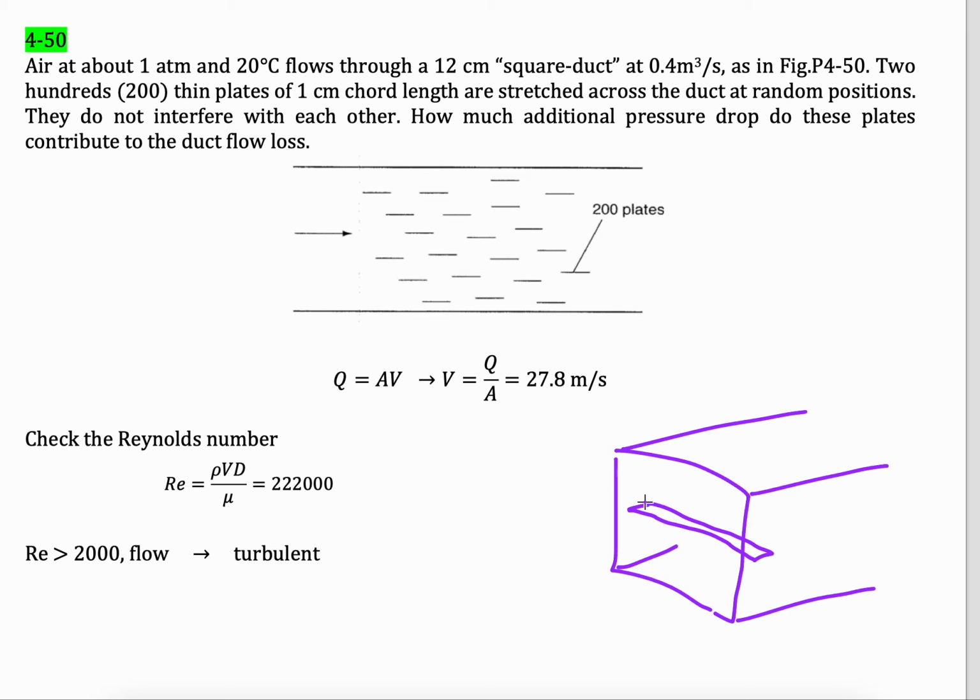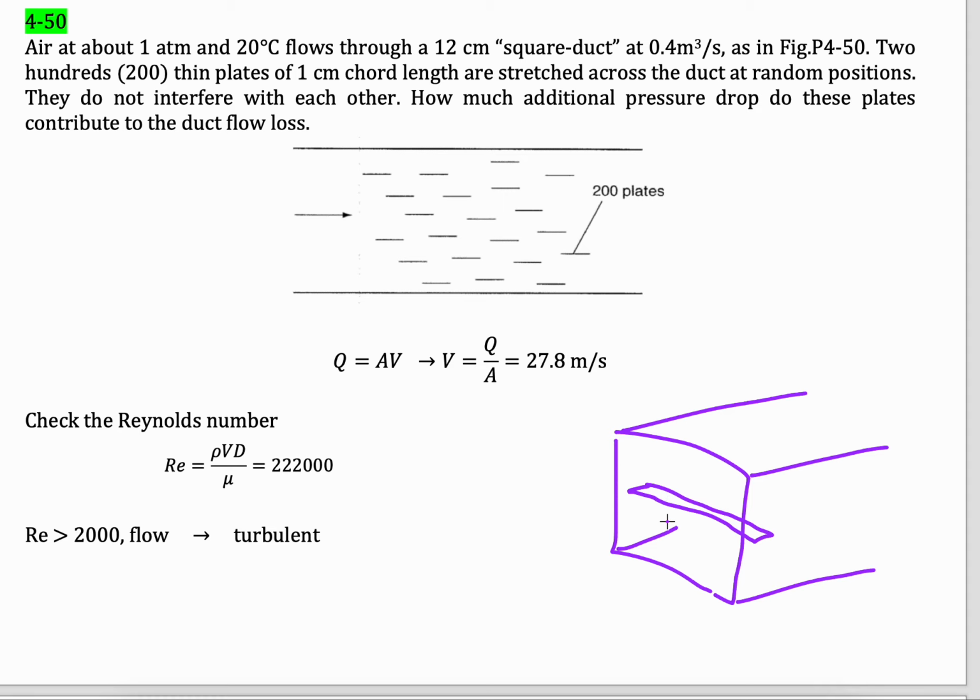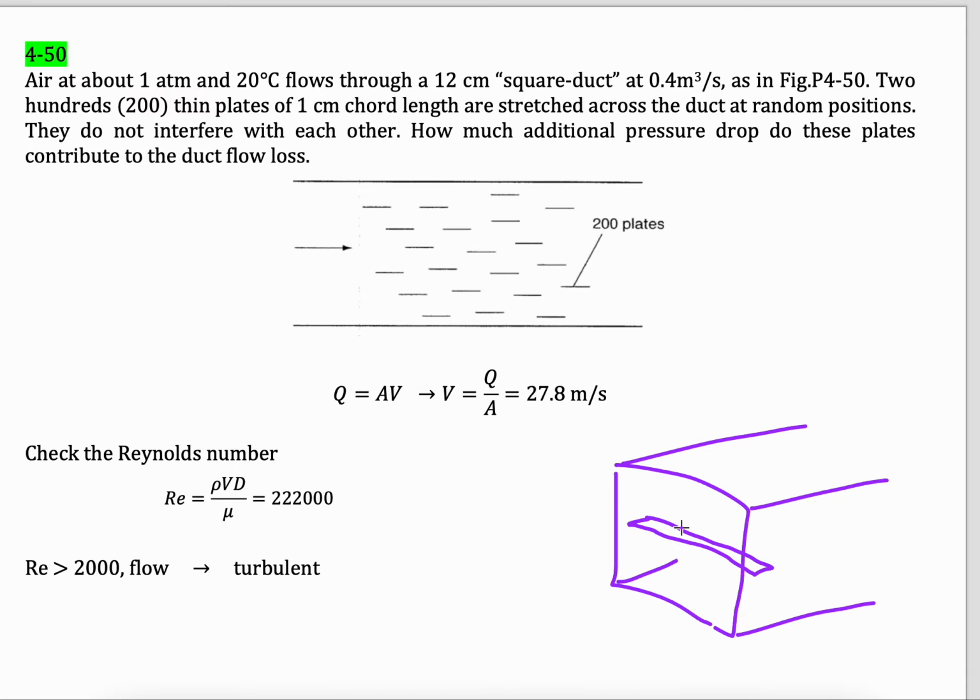Okay, and then the idea is when the air flows inside this one, it will create a boundary layer on this plate, and the boundary layer is actually the resistance. It will change the velocity. So when you give a lot of resistance inside a pipe, inside a duct, the pressure will drop. So this idea is actually we could drop a pressure for a fluid flow inside a duct without having too much phenomenon like turbulent wake and so on, because the plate is very thin.